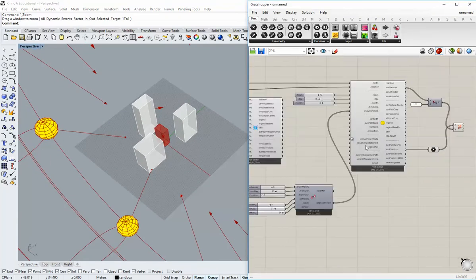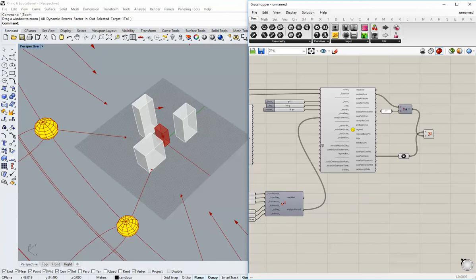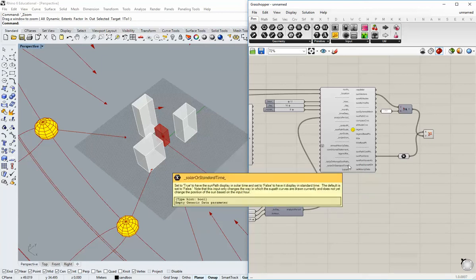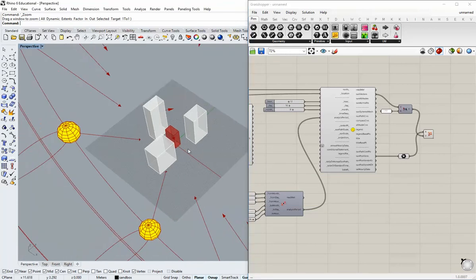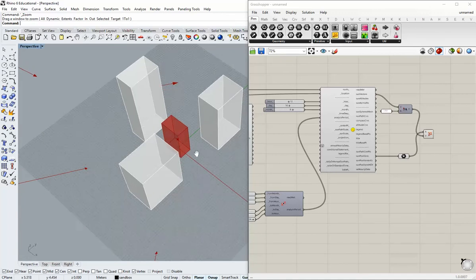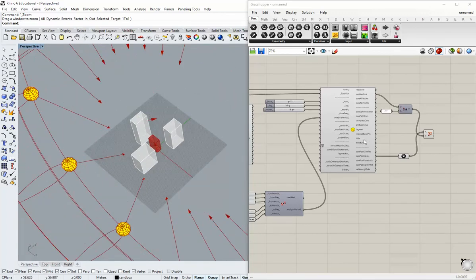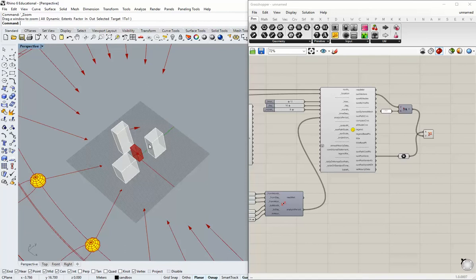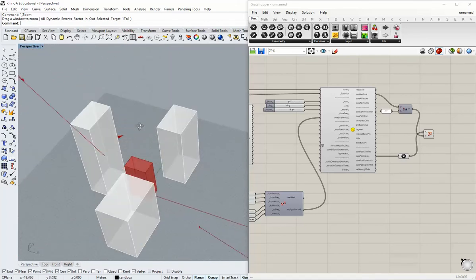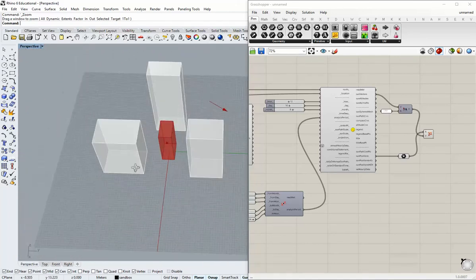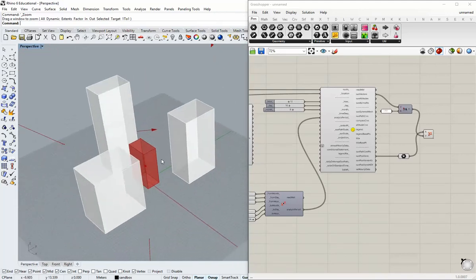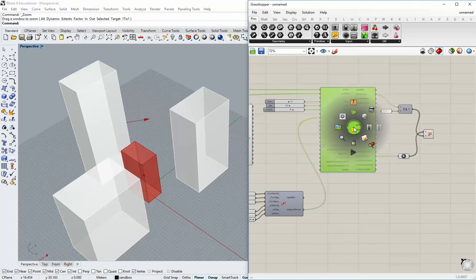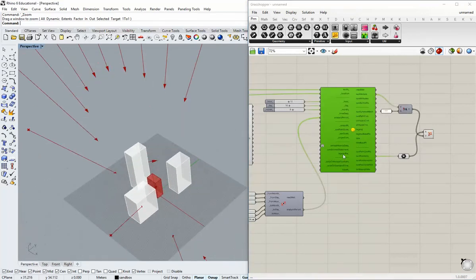Okay, and let's build on this. We're going to do two last things. One being the sunlight hours analysis. So how many hours of sun within a duration do we get onto our building? So this will be related to the radiation analysis, and you can also relate this to the sun path diagram if you'd like. The other thing we're going to do is some shadow analysis, and I'll probably end there because the shadow analysis, or the shade analysis, is another one that I think is also required of your studio analysis project. I'm just going to turn this one off, and I'll turn these off.